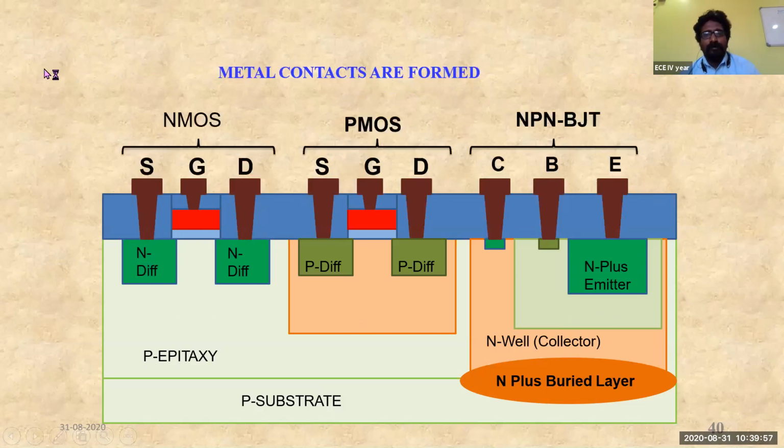And you can see it now. This is how the entire Bi-CMOS integrated transistor has been formed here. The metal contacts have been formed here. Wherever the contact cuts have been used, there we'll be diffusing the metals, mostly aluminum, in order to form these three terminals.